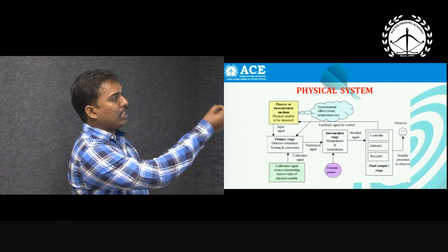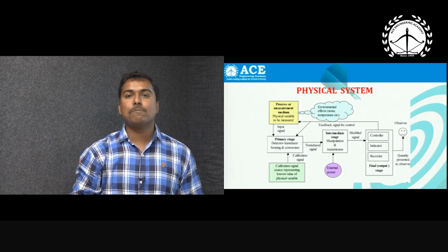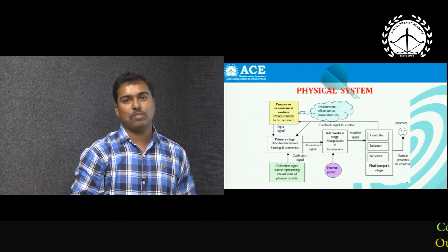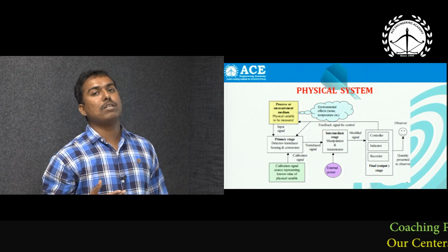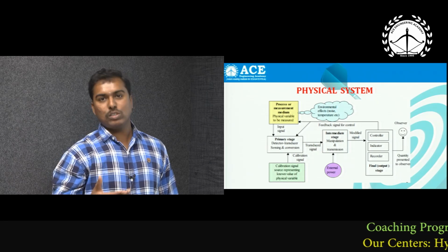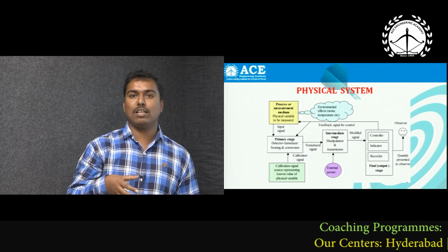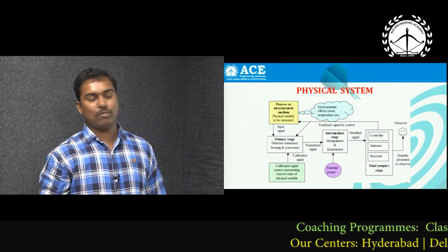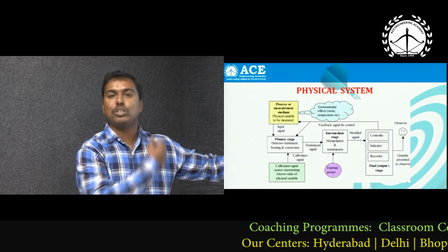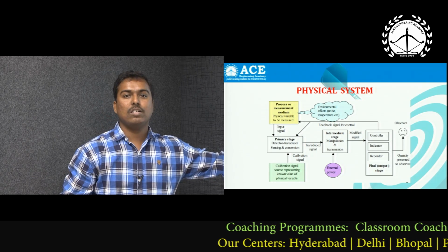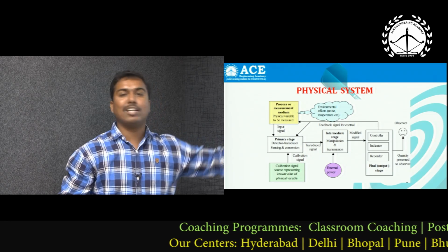In the industry, we are taking one non-electrical parameter. See that bubble type of image, there are environmental parameters. Those environmental parameters are nothing but your mechanical parameters. The parameters can be a pressure signal, a flow signal, a noise signal, a temperature signal, a force signal, a speed signal, or an acceleration signal. So from the physical atmosphere we have to take input, and that is done by the sensor. The sensor will convert the physical quantity into an electrical quantity.